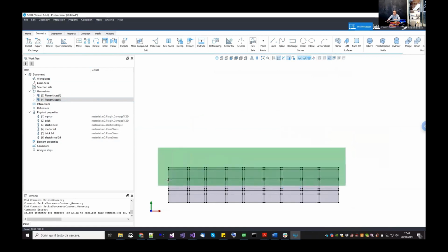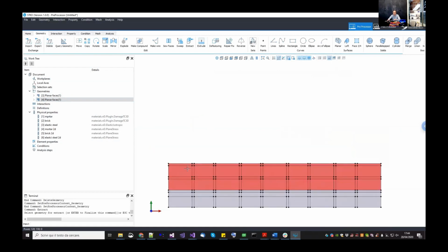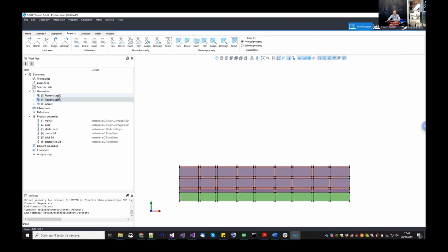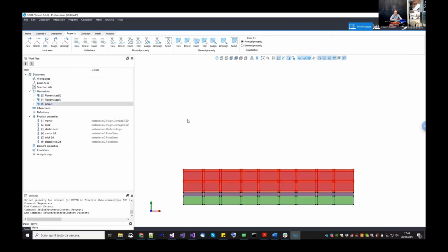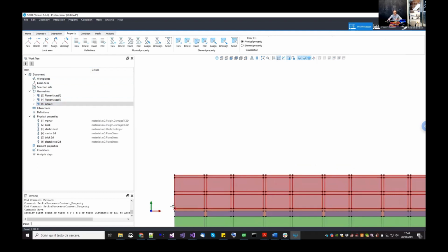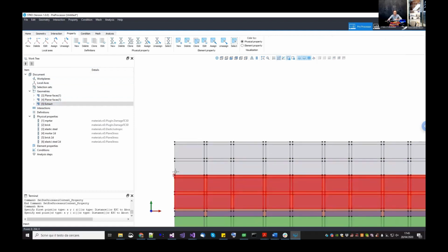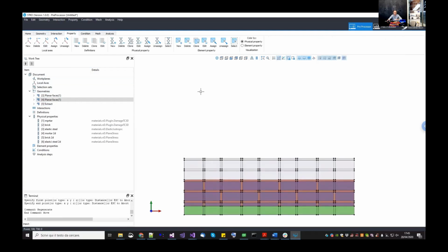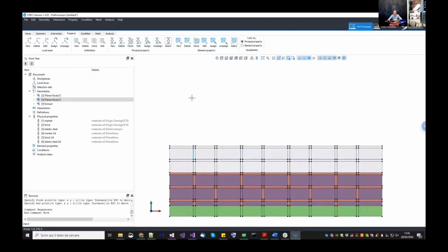Now what I want to extract is this regular pattern. So layer of bricks, mortar, bricks, mortar, in such a way that I can copy paste them, okay? Right click. If I go back in property, I can select the second one of the extract one, select, and I move it. I can click on the move command, or I can type the command here, pretty much like in AutoCAD. And now I want to move it from here to here.